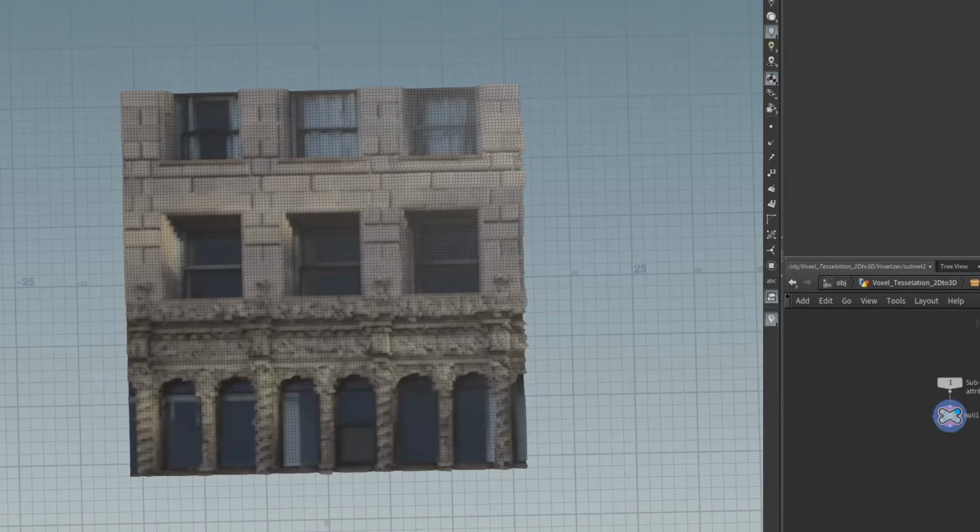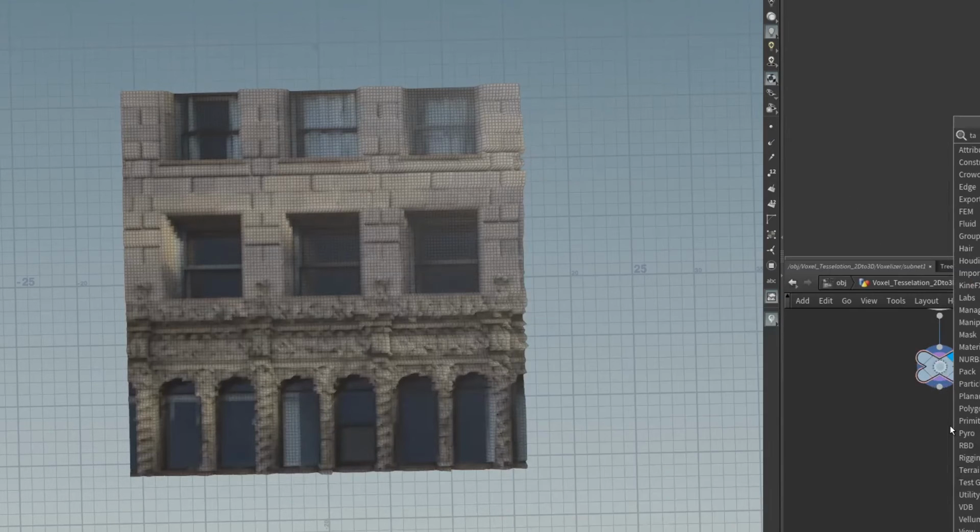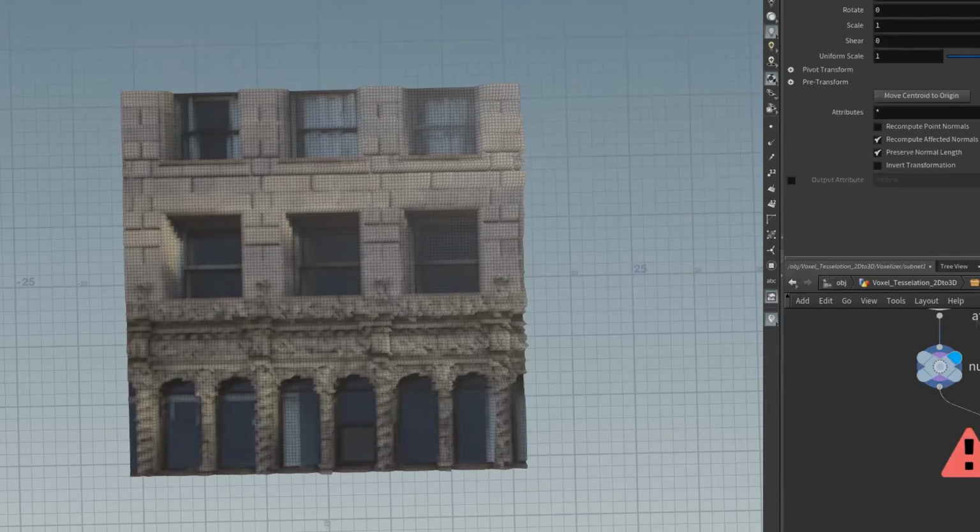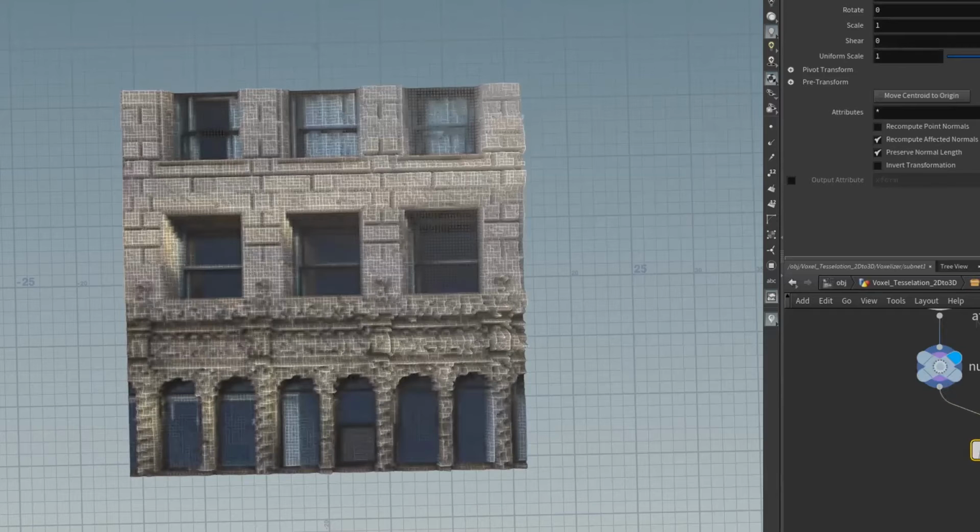We now have it here, and what we want to do is prep the image to be voxelized. So how do you do that? We want to make sure that everything's in the center. How do you make something centered? We are going to define the center of the geometry by typing in something here. Something very nice about Houdini is that you can put some very simple code within all these tabs.